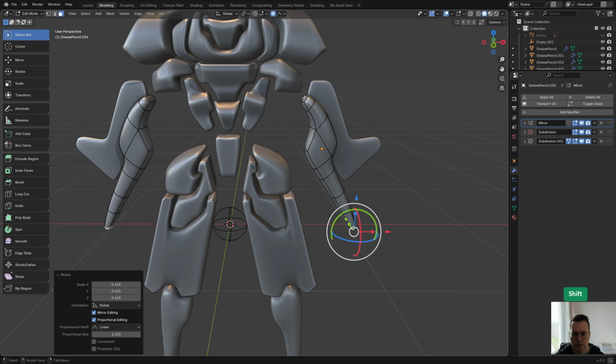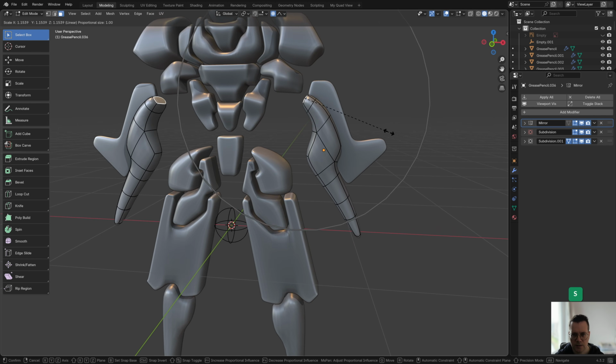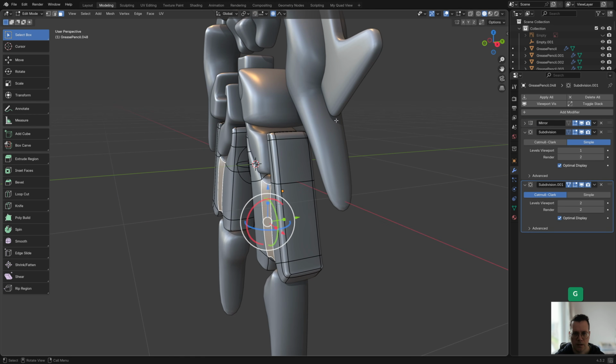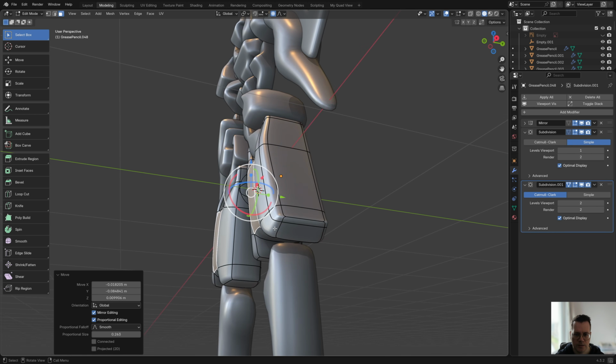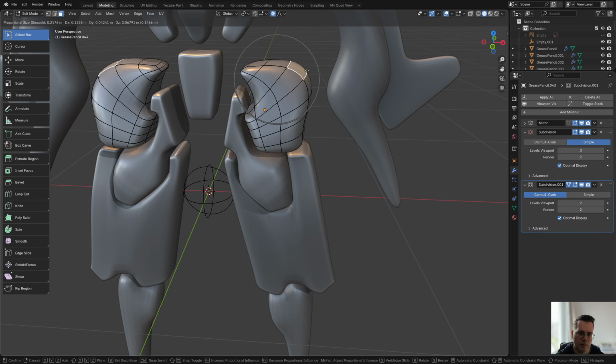And we can adjust the shape here by selecting this face and then maybe scaling it up from there. And I will just decrease the radius slightly. And so that's another way to control the shapes as well. And you can also set proportional editing to smooth, and it can be very helpful to quickly adjust some shapes. So just adjust the falloff by scrolling the mouse wheel up and down. That way you can really control how you're affecting the shape.